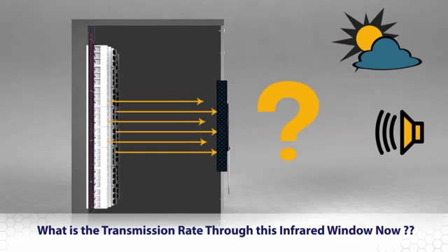So again, with all of these contributing factors, what is the actual transmission rate of an infrared window? If the materials, like the fluoride-based materials, are hygroscopic and susceptible to high frequency noise and vibration, their transmission rate can change at an unknown rate. We've had them fail in as little as 10, 11 months, where some have gone on for several years. So it's really unknown, but it's a fact that these things do change over time, and working out what that change is is very important.